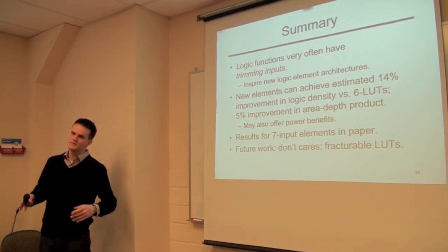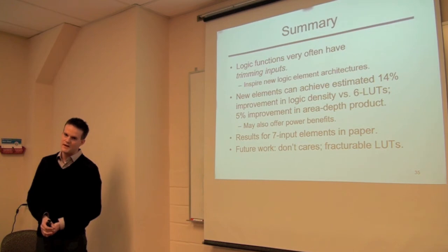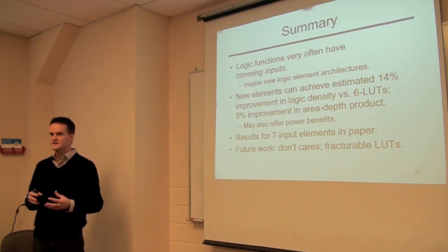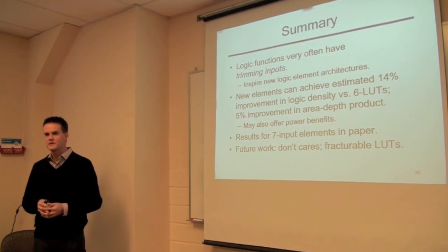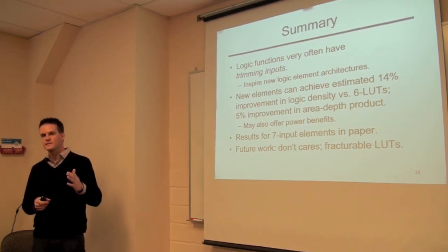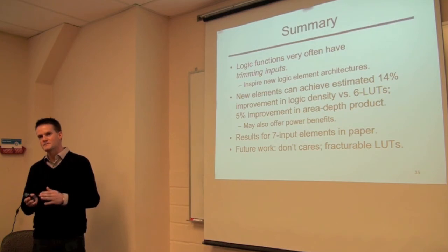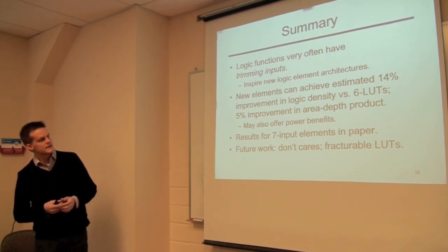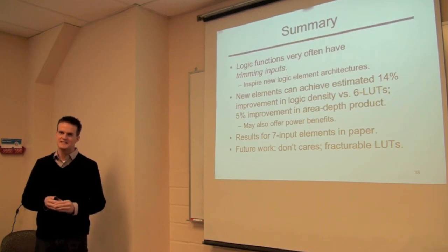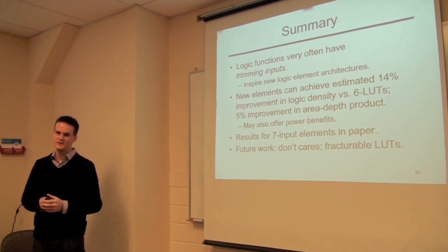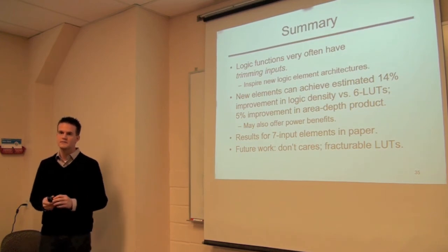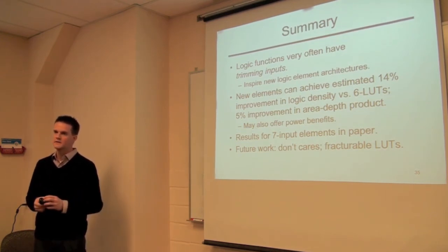But on the other hand, if your tiles are smaller, then your wires and capacitance will also be shorter. So you may get some delay improvement from that. So it's not necessarily that you would actually lose performance. You might get flat performance because your tiles will be smaller. Even with the 5+4, we're seeing very similar depth, but it would have smaller tiles, so it should have shorter wires and better delay than 6 LUT. But you're right, it's a very good point, and we would like to investigate that. It's kind of hard to investigate, but basically, when you lock a signal to a pin, do you lose routability? How much do you lose? Does it cost you in routability?